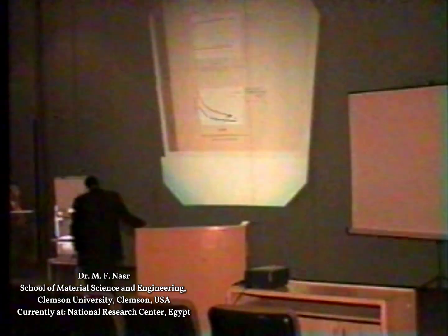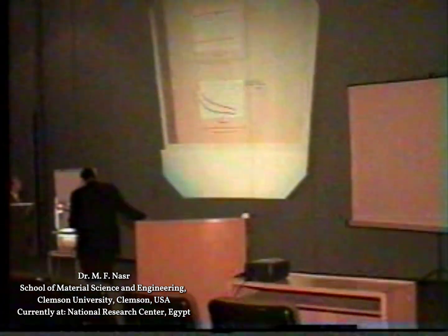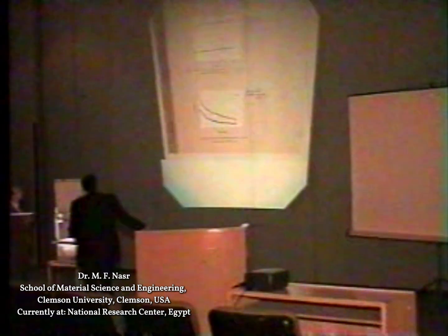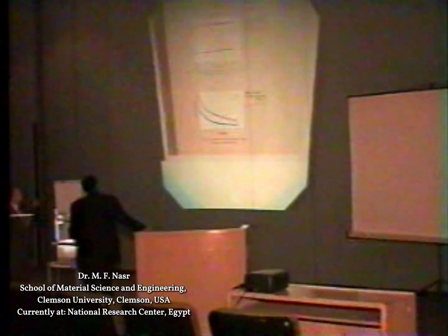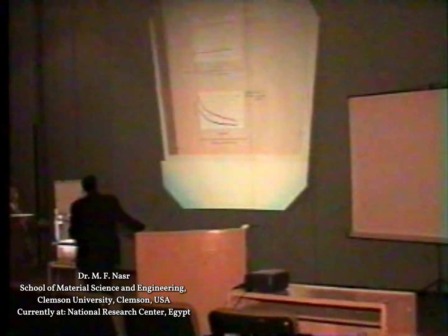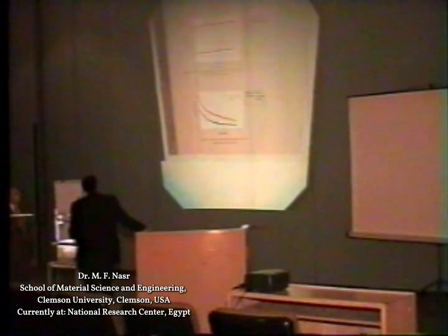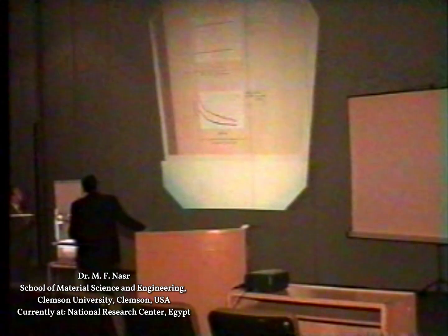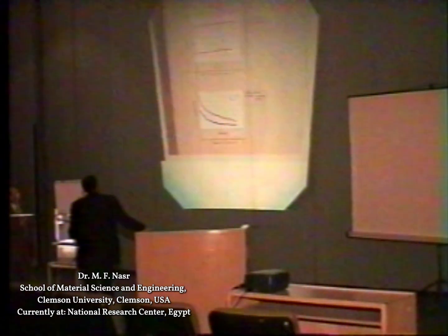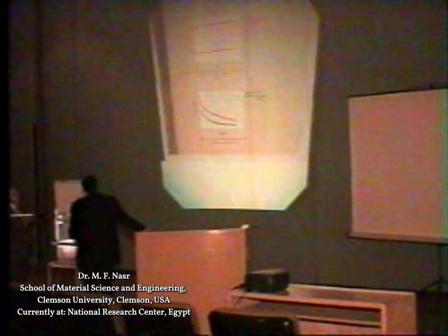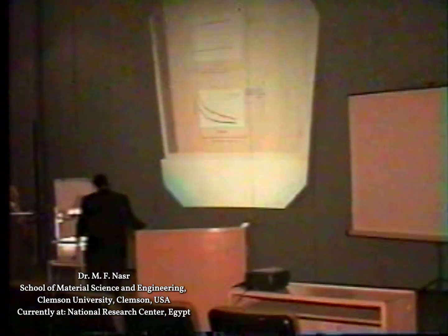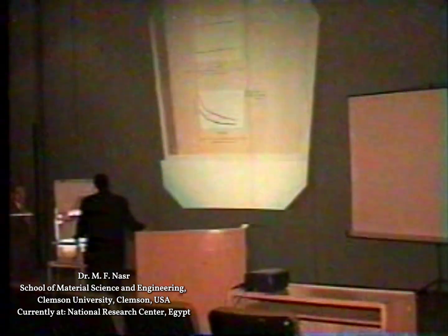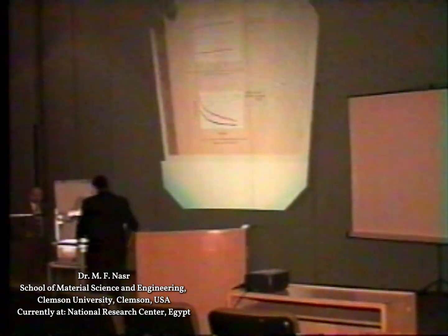The interesting criteria we found is at above 4 volts, here we measure at 5 volts, we discover a very interesting thing, which is the discharge effect, because I apply more potential and all the electrons hop or move through the crystallite and charge. And as soon as I let the voltage be stable, here we have a discharge effect with time, because the electrons already jumped or moved at higher voltage. So we have charge and discharge voltage, and this criteria needs to be more studied, and that's what I'm doing now.